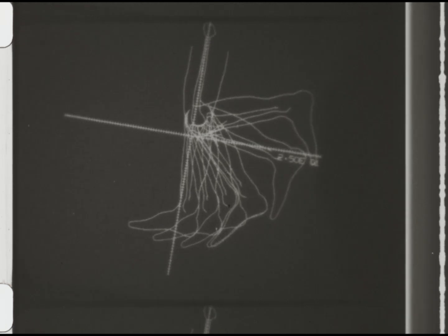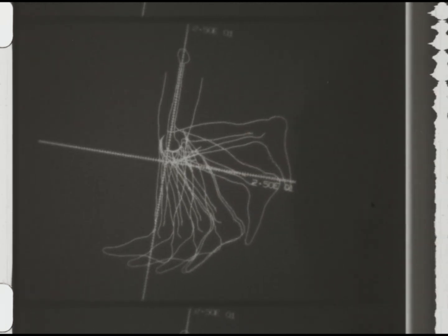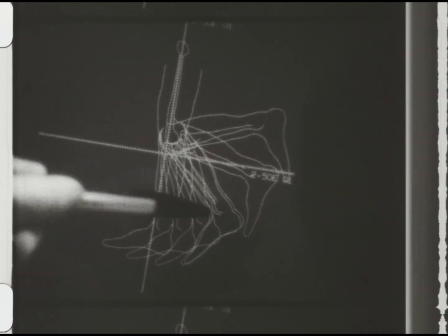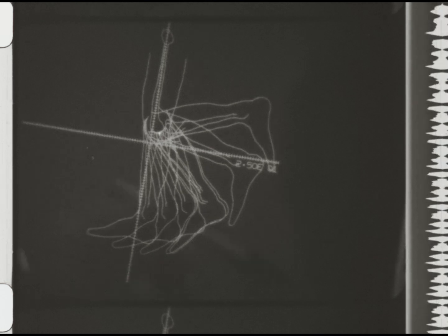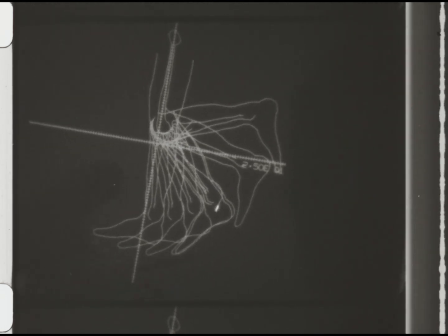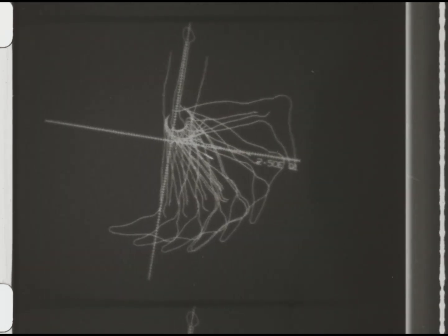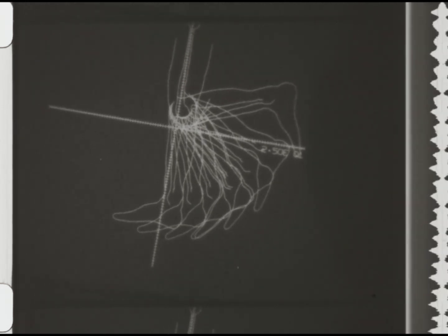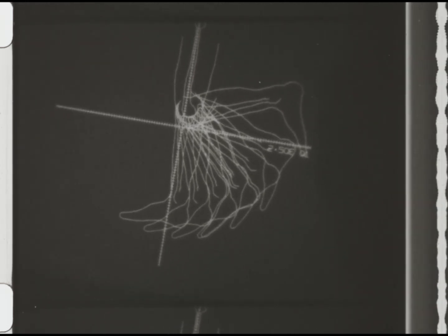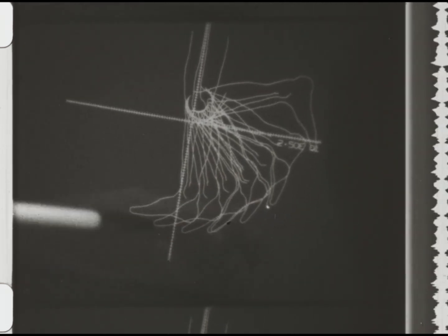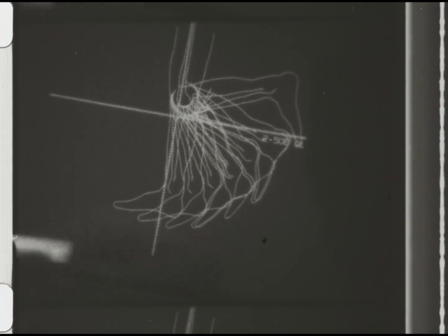This is not an approximate solution. It looks as though this move missed that second design position. That's not really true. We draw the mechanism in certain widely separated positions so as to avoid cluttering up the screen. We can move it back actually and show you that the leg does go through exactly that second position.